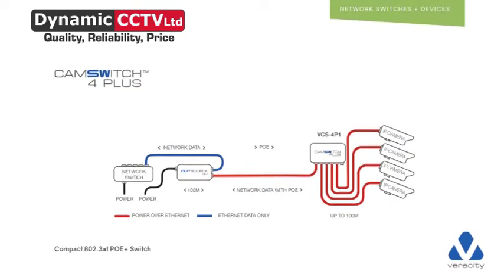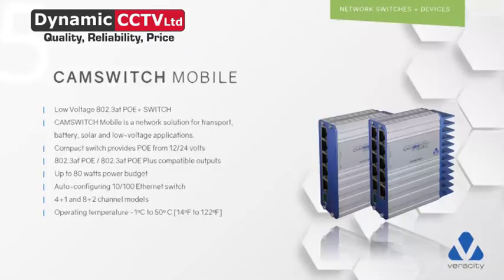So again, bear in mind how many watts you want at the end. Do the calculation for your total wattage for the site, and then you know exactly which injector to choose, so you can achieve what you want to. More importantly, your cameras will turn on at the end, and when you've left the site, the IRs are going to come on at the end of the night. So quite an important step.